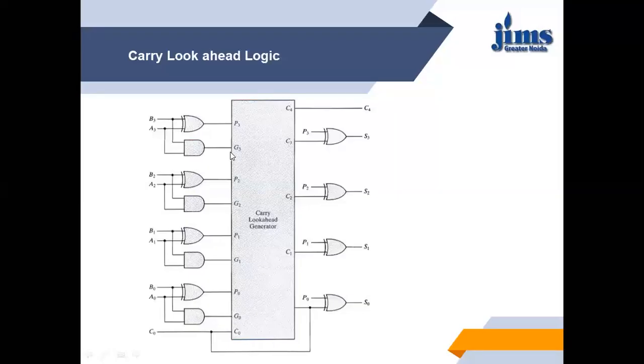So in this way, when we design our circuit with the help of carry look ahead adder logic, we are getting the sum and carry after an equal number of gate delays, and there will be no anomalous output change at the output when we are changing the inputs. So this is the way we get an equal and exact output without any unequal gate delay and without any anomalous change.